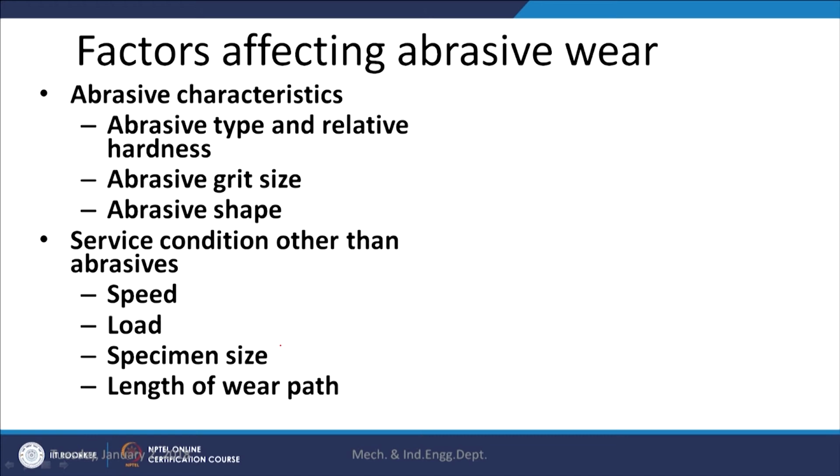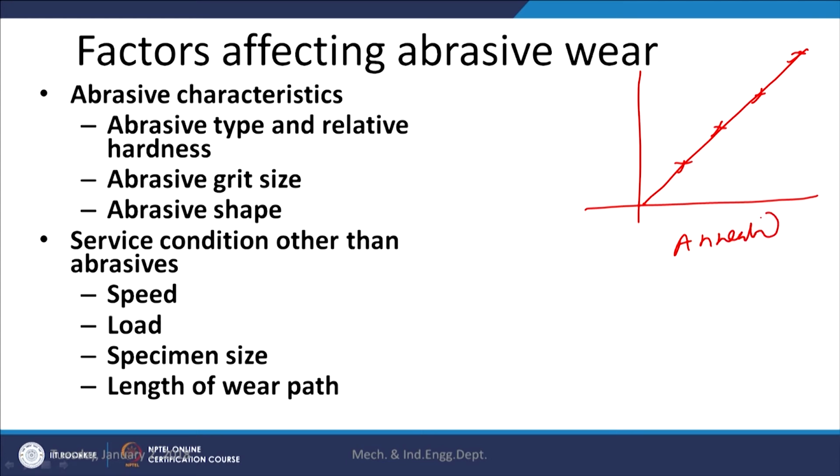So, now we need to see one simple diagram of how the material hardness changes. There are different metal systems which will be showing different values of hardness in annealed condition. Annealed condition means that the material is subjected to high temperature exposure for a longer period, so that it does not have any work hardening effect. So, soft metals like silver, then aluminum, then iron, then cobalt, may have a variation in the hardness like this.